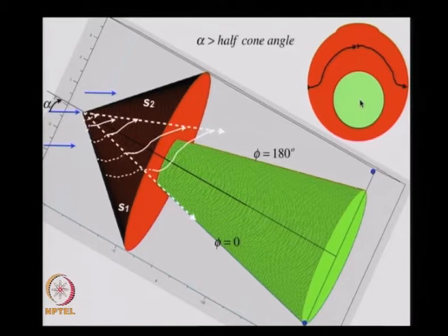Here this is the streamline, which is this one. This streamline is above; it is no longer sticking onto the surface of the cone. Again all these streamlines pass through this, as we learned before, and therefore we will still have this point here, but the vortical singularity point will actually be lifted off the surface of the cone and somewhere over here.